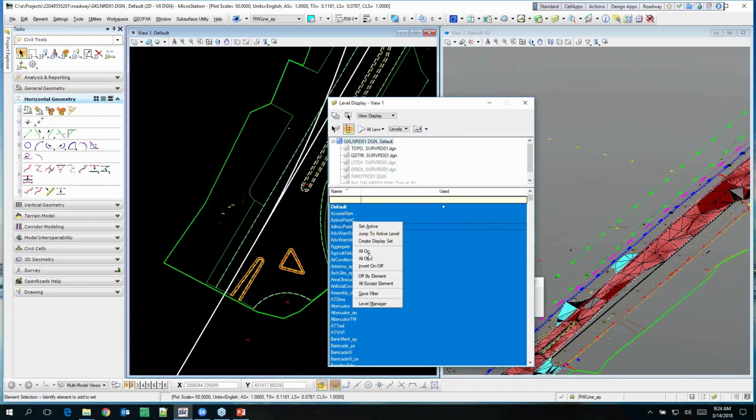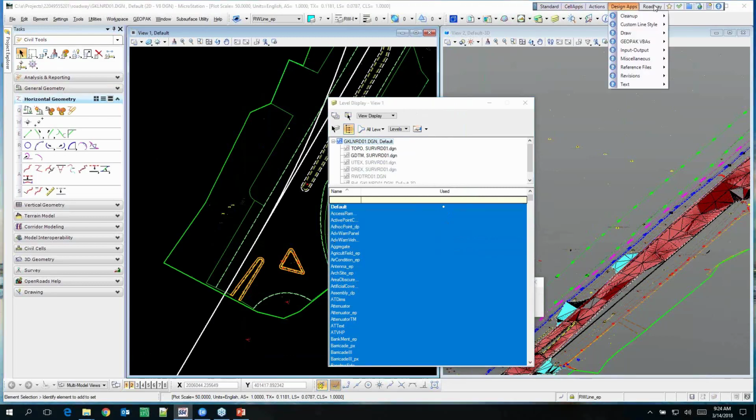But they have to be at the terrain level. Right. So in 2D, they're just there. All you do is add a profile to them in the 2D view, which makes a 3D line in the 3D view, and then when you slice through it, it goes back to 2D. It thinks it's a feature, and it puts a right-of-way symbol cell. That's why it always sits on top of the existing ground, because that's where you set the active profile for it.